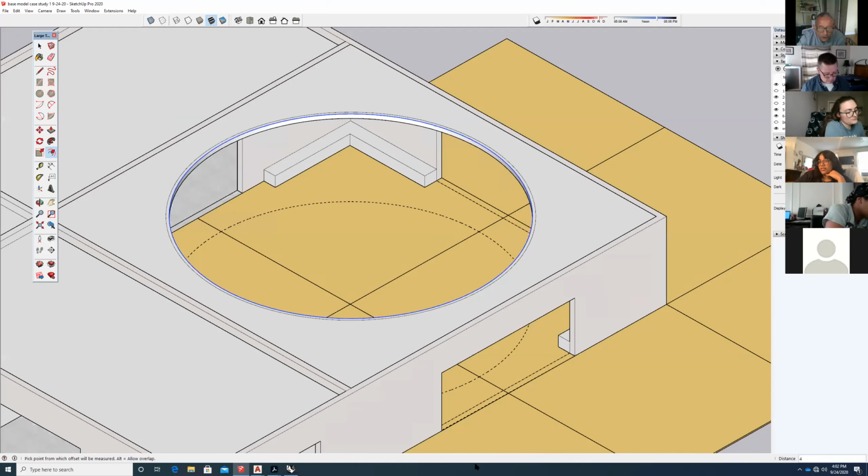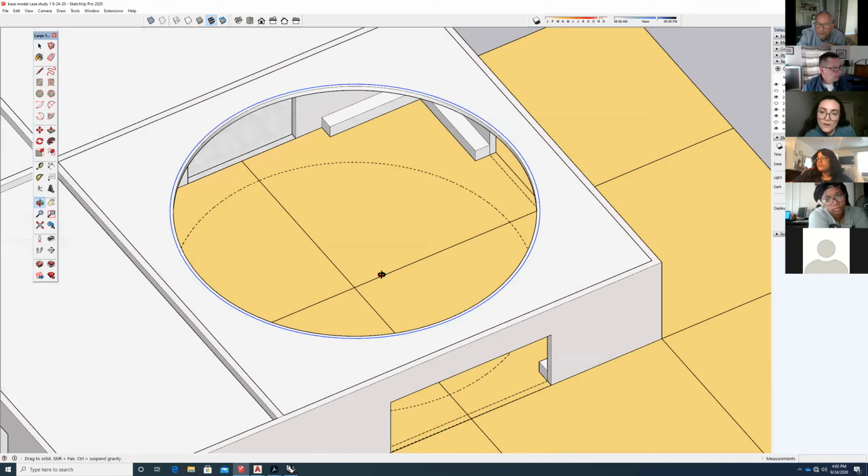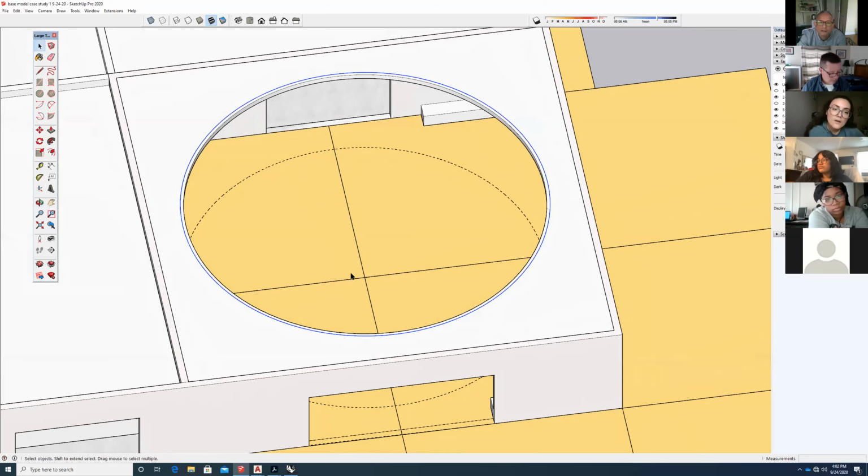And then I believe this guy needs to be 12 inches thick. Okay, so I want to pull up the parapet, then I'm going to move the roof down. I could do that in another order. So I have to be really careful in my selection. Push-pull this up.